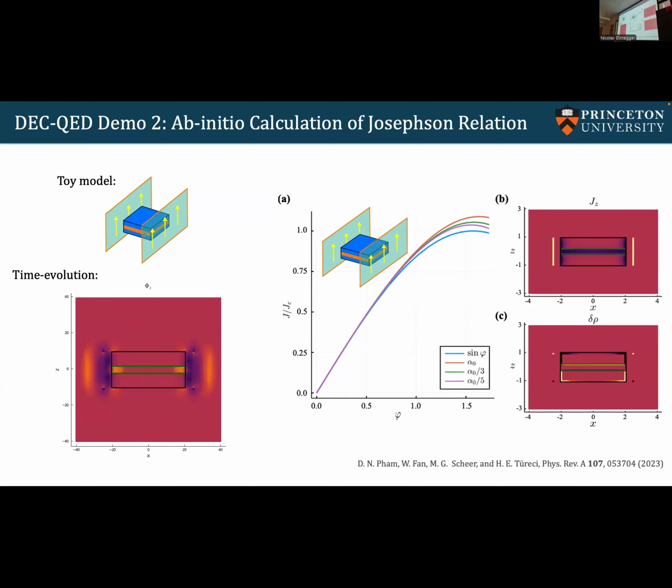So yes. This toy model, is the input a mesh file? Yes, it's the mesh. Is there a certain structure to the mesh file for it to work with the package? Right now it works with just DGS or Gmsh, and you can just load it in and run the simulations. In this case, you have some volume, some surface. Are you assigning any ports to the mesh file? You need to have the information about what surfaces you want.